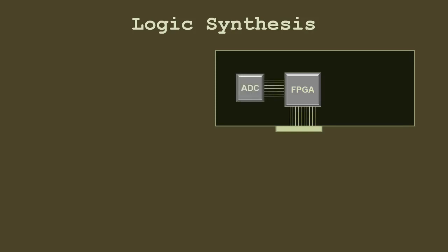And that board will be connected to different interfaces depending on the design. We might want to communicate through a communication link, and maybe we want to sample some data using ADCs. We want to maybe see the status of some things on LEDs, maybe connected to push buttons. This is a poor diagram for a push button, but anyway. And we might also want to connect it to some expansion connector with pins going out to some other board. So these are pins. If they're not looking like pins, that's my fault. Forgive me for my drawing.